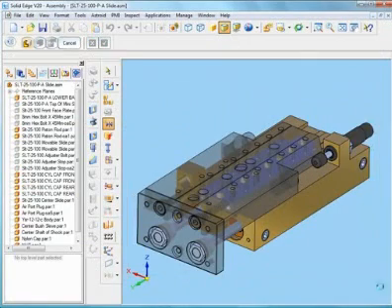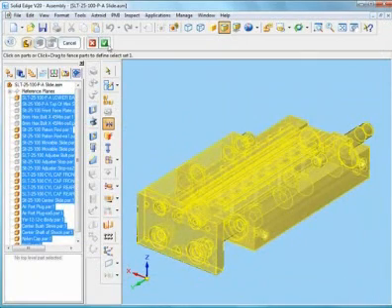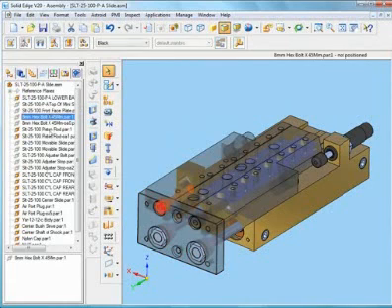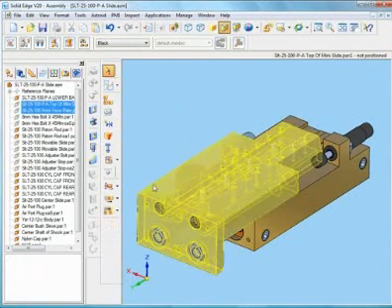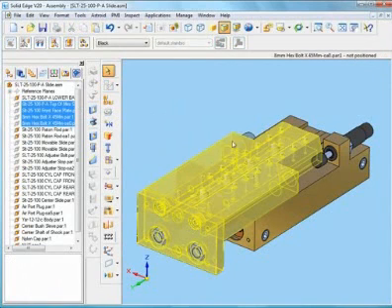All of the parts are initially positioned using a ground relationship. This means if a part is moved, it will move independently of surrounding components. Auto-constrain can quickly remove all grounded relationships at once.